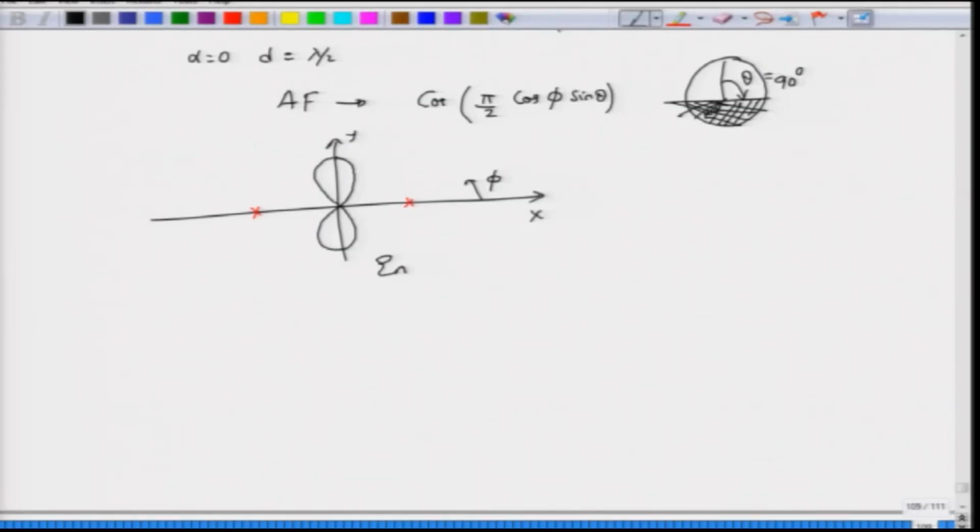On the other hand, if you are on the x axis, the antennas are along my thumb, which is along the z axis, but now you connect it in this way, right. Now, if you are looking for the antenna array factor here, you know that the radiation from this antenna onto this one will reach earlier than this fellow, and what is the phase shift that you are going to get because of this path length difference of lambda by 2? Lambda by 2 will give you a phase shift of 180 degrees. So, along this direction as well as along this direction, the overall field will be equal to 0, right. So, that is what is captured here. This is called a broadside array.